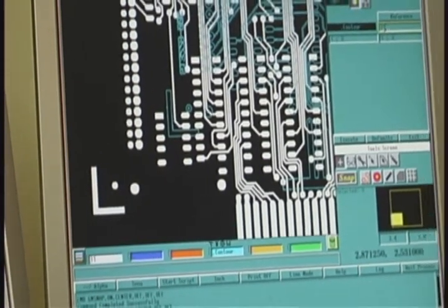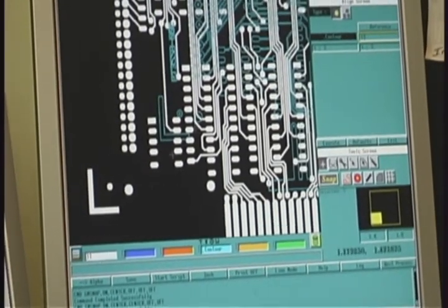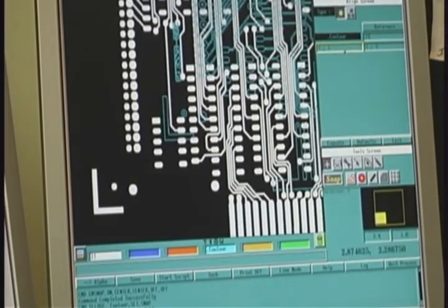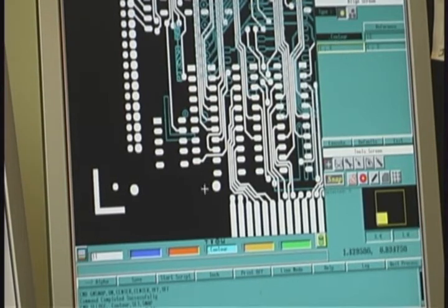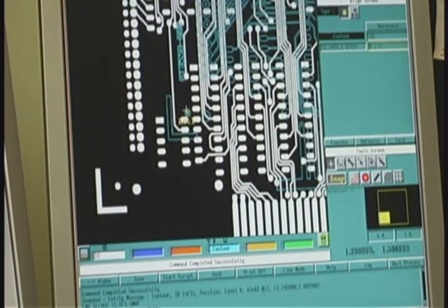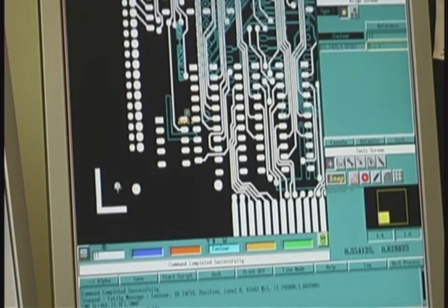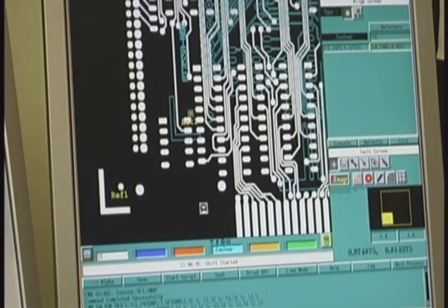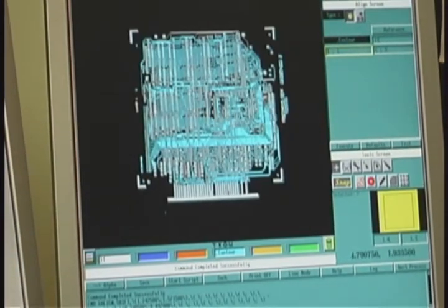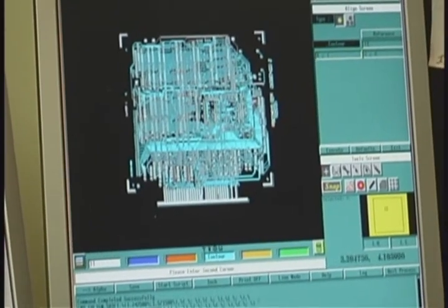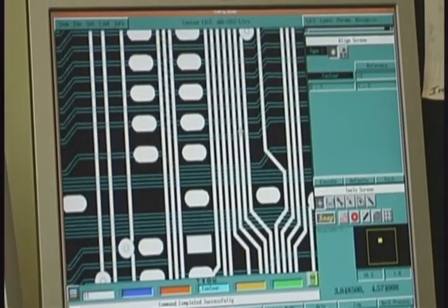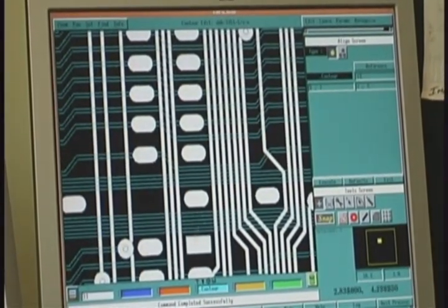We pick the layer, the reference layer, which in this case is layer 1. Then we make sure that we have the contour highlighted, and it will snap to the center of the feature and then snap to the center of the pad and execute it, and it should be pretty close to the alignment. As you can see, both layers are perfectly aligned.